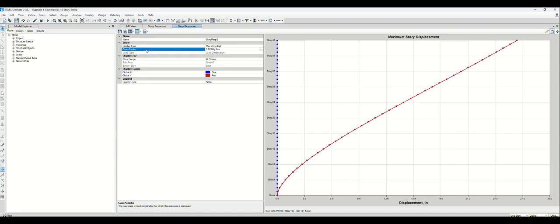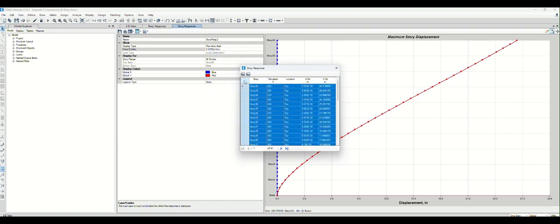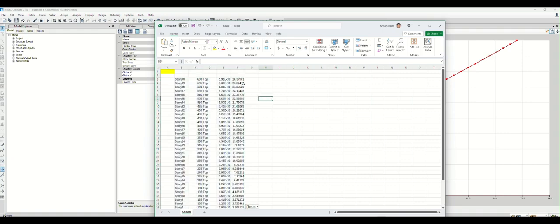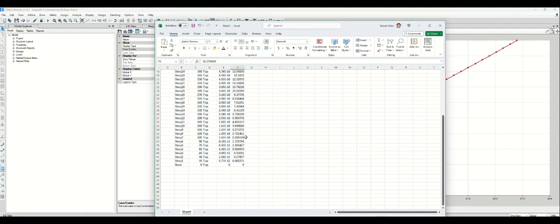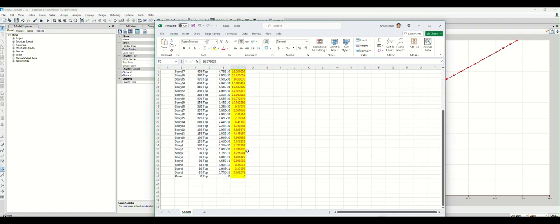So you can see that there are many ways you could pull out the data. I'm gonna pull it out. Click this Excel, format it. So you see all the deflections in the Y direction. I'm gonna select and copy, and I'm gonna put it here. So this is, let's say, deflection in Y, right? In inches. So we're gonna just continuously increase our stiffness, wall thickness,